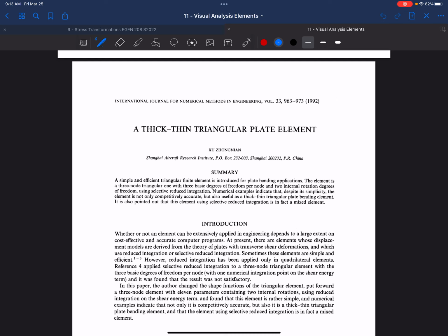Have you taken the concrete class? You designed a retaining wall in 400 or 500 level concrete, okay? It just simplifies it down there. You have your active or passive pressures, you have at rest if you decide that the wall's not moving, all of that stuff. You have your sliding friction resistance, all of that it takes into account, it'll design it for you. They also have base plate design, you can do it that way.